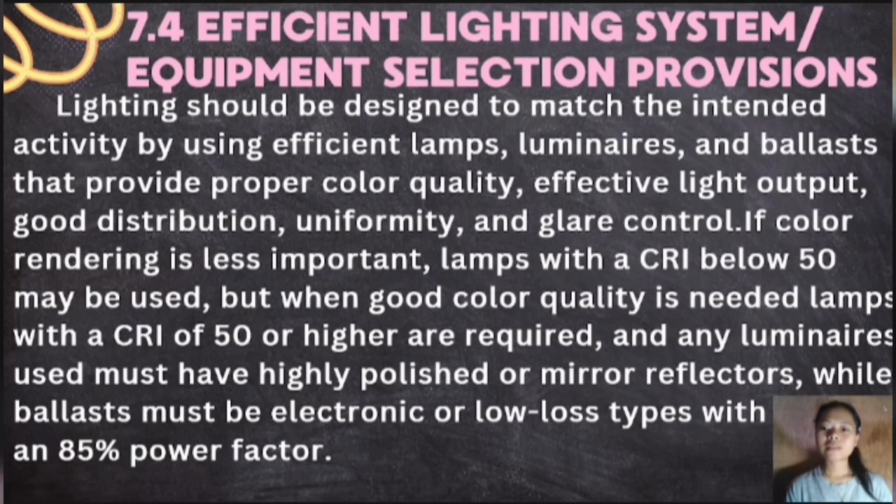The light must match the purpose. Provide enough and properly placed light, avoid glare, and maintain good light quality. Color accuracy is very important. Lamps with a CRI, or color rendering index, of 50 can be used, however, for good color quality, CRI 80 or higher.